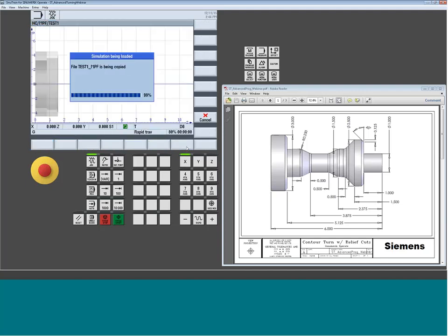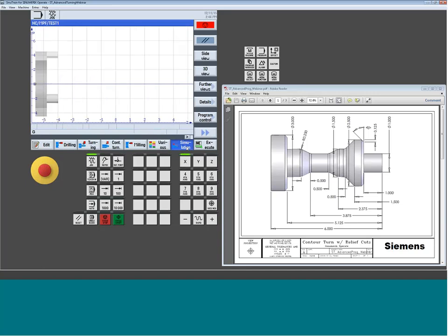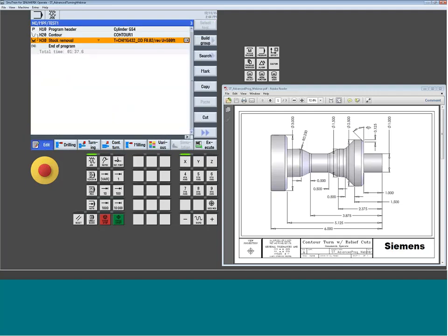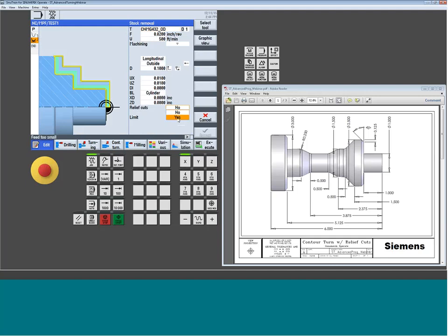So we're going to start to machine the part, but it's going to blow right over the pocket. Here you'll notice it's not even going to enter. And this may be an appropriate strategy. Even though I drew the whole shape, since that tool doesn't have a lot of relief, I may not want it to even try to enter it. But if I do, I have to first trigger it by turning on relief cuts.